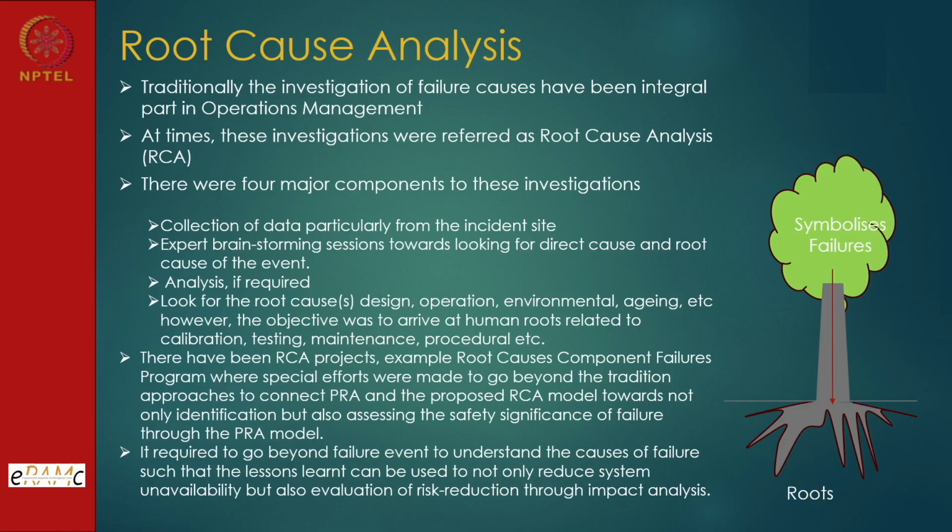There were four major components of root cause analysis traditionally. So first is, if any incident has happened, then immediately visit the site and collect all the information: what we saw, what we found, what was the noise level, how it affected the area, how it affected the plant. The objective is to collect this before we clear the plant and have a cleanup. We have to collect the information, what kind of signature material was found. So data collection is one thing.